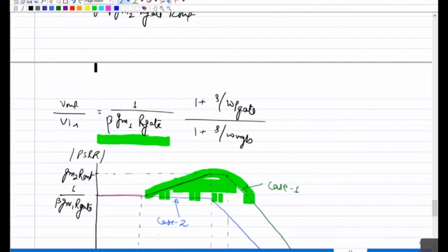That's why most of the time your PSRR in dB is negative. So when it increases in negative, your PSRR is improving. When it is reducing in negative or increasing in positive, your PSRR is degrading. So don't get confused with the term high PSRR; more negative means it's lower, not higher. Sometimes people get confused with that.